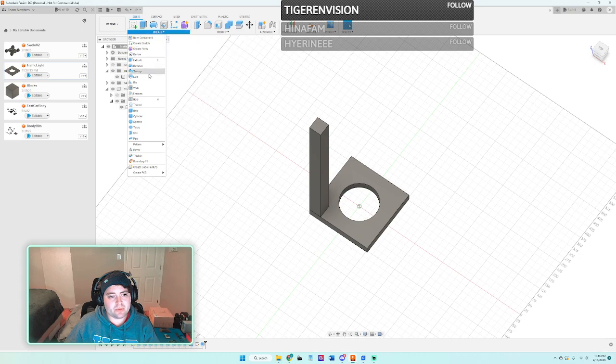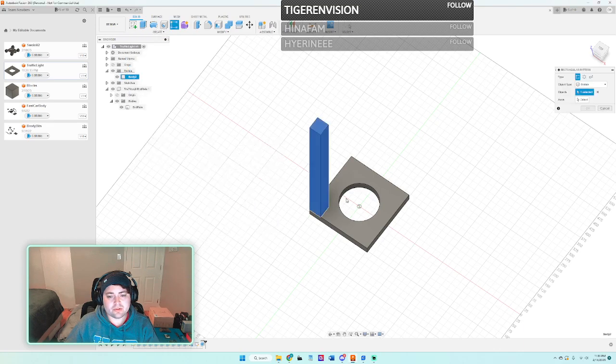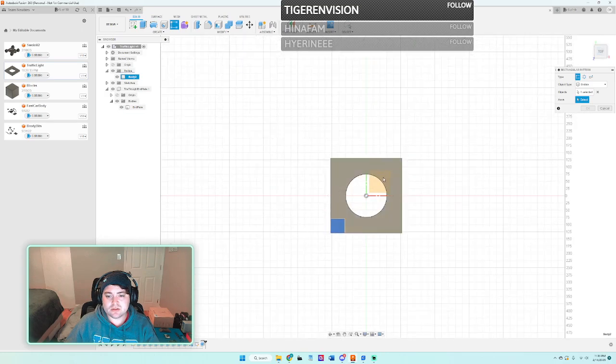So with that, what we can now do is make a rectangular pattern using this. We're going to say that the axis is along, well, here is fine. We only need a 2 by 2, so let's set that up, 2 by 2.